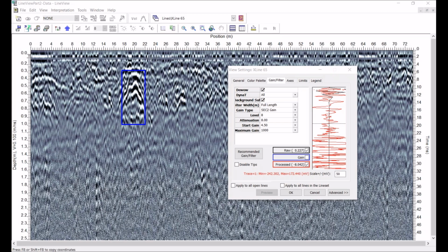Does elevation consider off-nadir look angle of the antennas? No, it doesn't. Not quite that clever at this point. The position of the trace is actually just moved up or down. So it's a very simple correction. It doesn't take into account the beam direction and that sort of thing. And you're absolutely right, on a slope the antennas will be tilted and the GPS position will be shifted. Yes, that's all true, so we do not take that into consideration. But in actual fact, if you look at the geometry, a lot of times that angle is pretty small, so it doesn't affect it that much.